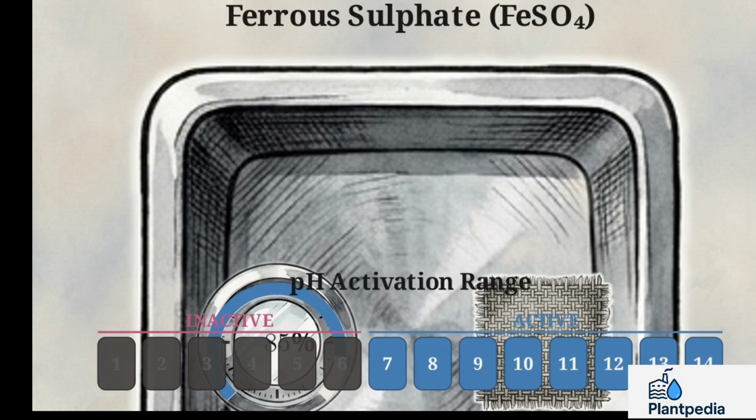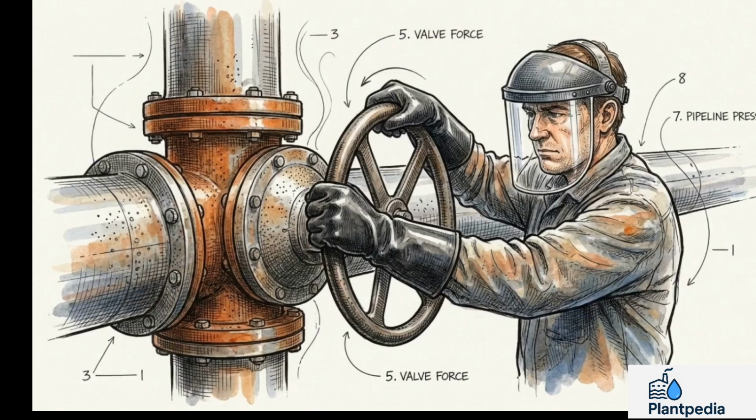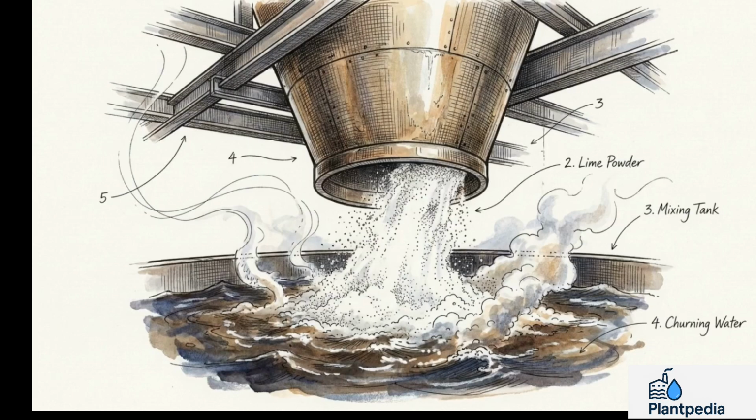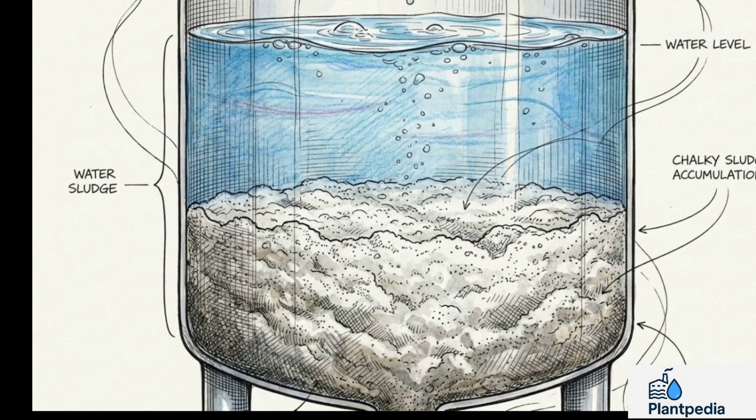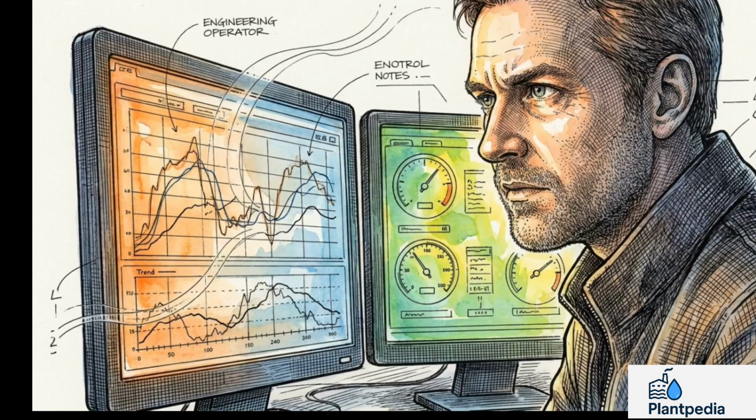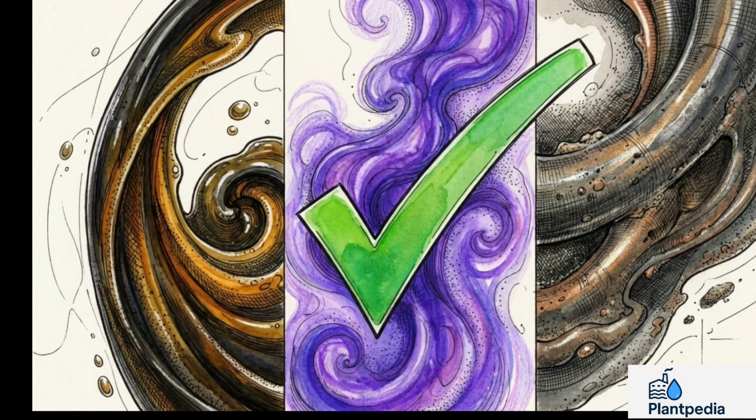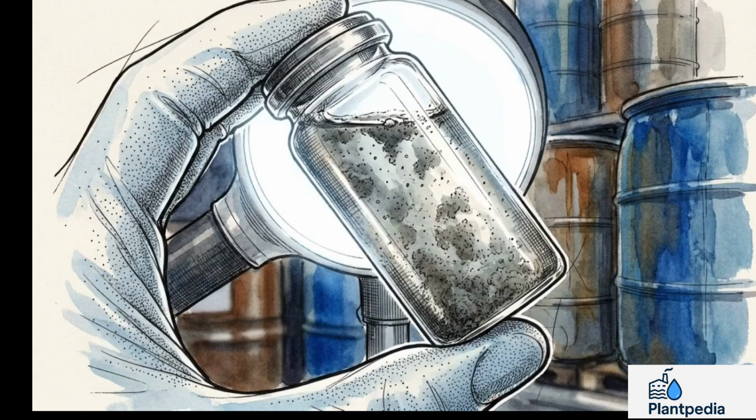Its critical operational flaw, however, is that it completely fails to activate in low pH acidic environments. To bypass this flaw, operators are forced to implement a mandatory workaround, artificially driving the pH up to the alkaline side by dosing the water with lime. Adding that lime creates a compounding problem, hitting the plant with a heavy sludge generation penalty. Iron coagulants demand high operational discipline regarding corrosion control and pH adjustment. But for oils, dyes, and heavy industrial pollutants, they are the only viable options.